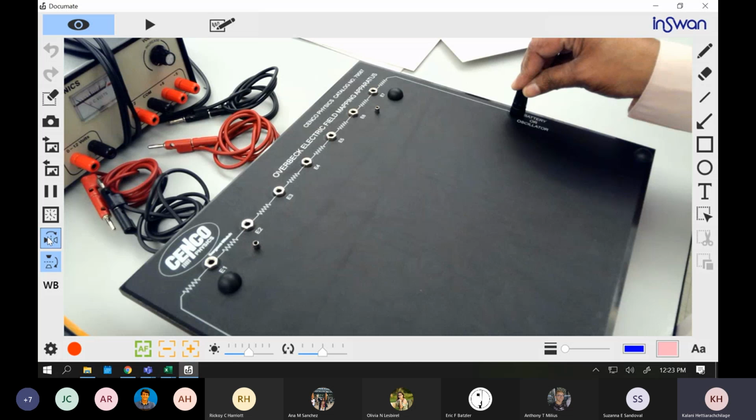And then the other end of the red, you're going to connect into your equipotential board onto the left side. And then take the black one, connect into the power supply black side and to the right side of the equipotential table. And make sure your wires are not on the table, keep them by the side.